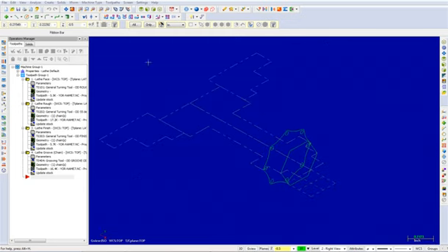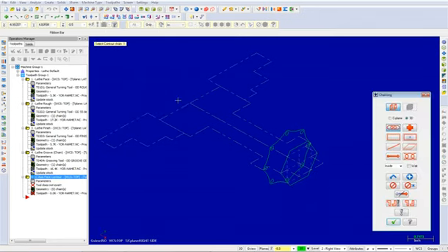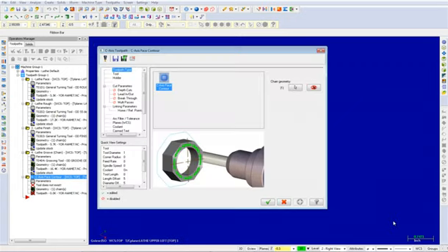From here, select Toolpaths, C-Axis, Face Contour. When the chaining dialog box appears, select the 6-sided polygon we created and pick the OK button. The C-Axis Toolpath dialog box will appear. Down the left side of the screen we have a tree view list. Here is where all the parameters can be found, selected, and modified to create your toolpath.